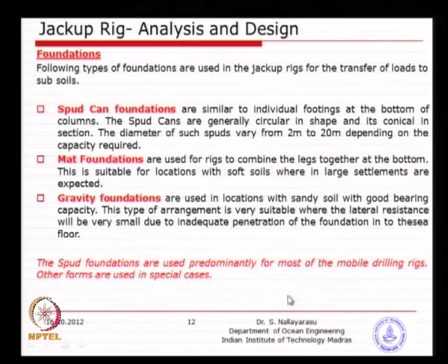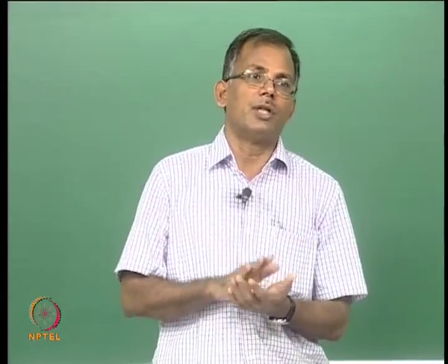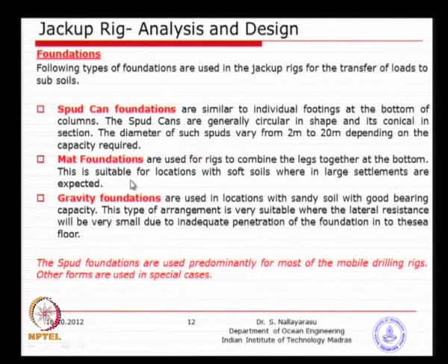So, these gravity foundations do have some amount of embedment into the ground, but not substantially, maybe 1 meter, 1.5 meter. Whereas, if you look at the Spudcan or mat type of foundation, they have to go through sufficient depth, so that it gets enough bearing capacity as well as enough horizontal resistance against sliding and overturning. So, we will see some of the pictures, you will be able to understand easily.